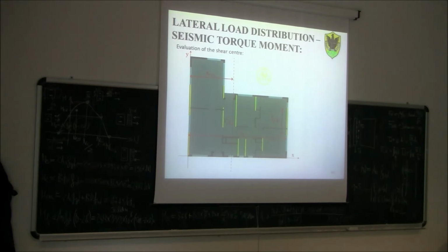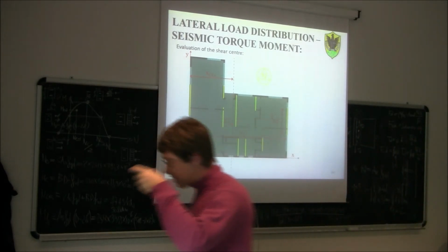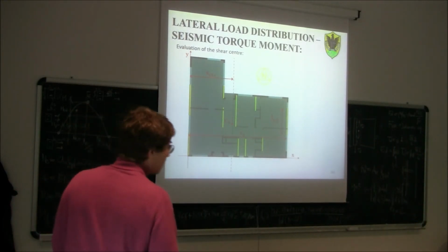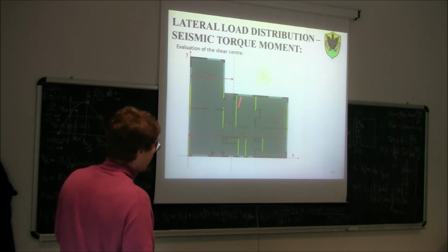How can we calculate the center of stiffness of our wall system? The center of stiffness, in this case, will be the centroid of the distribution of lengths, since the stiffness is proportional to the length.